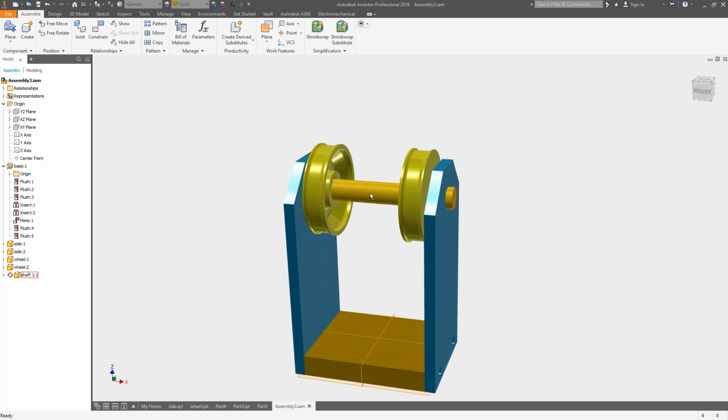Because, you know, this is Inventor, right? You're reusing these components. You're hopefully running Vault and making sure that these components are being reused, and you're not creating redundant geometry. Well, if this shaft is adaptive and it's used other places, guess what just happened to where that is being used in other places? It just changed length and potentially caused problems.